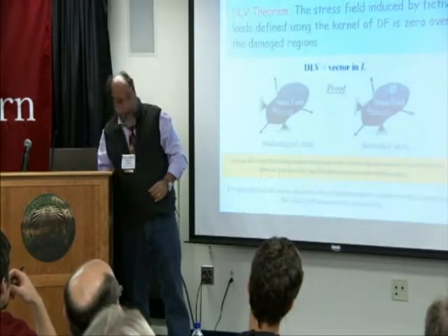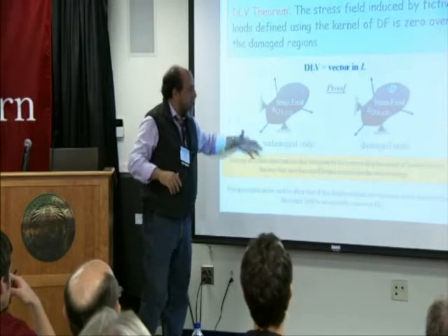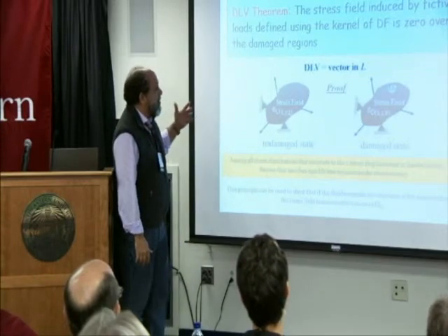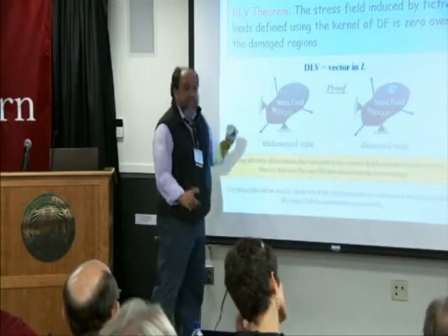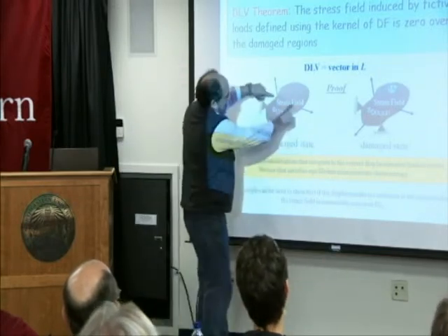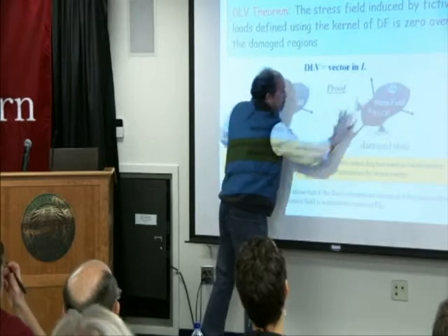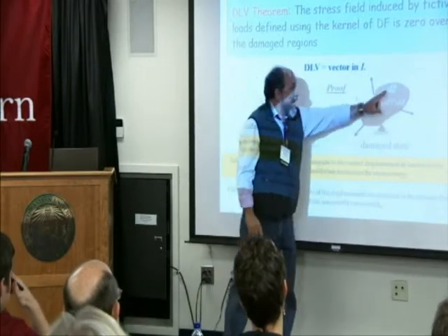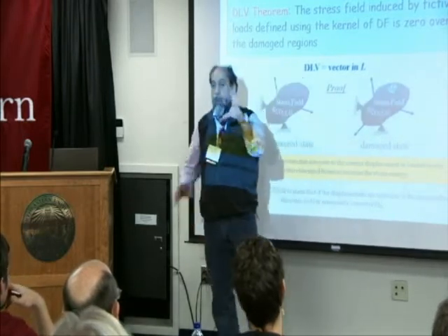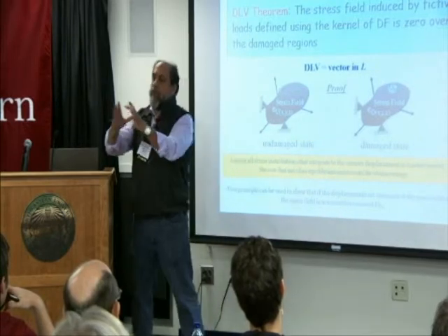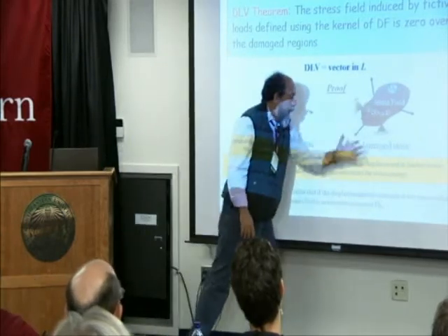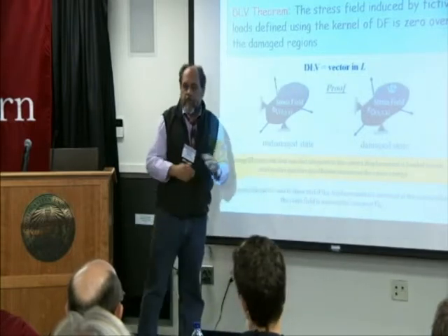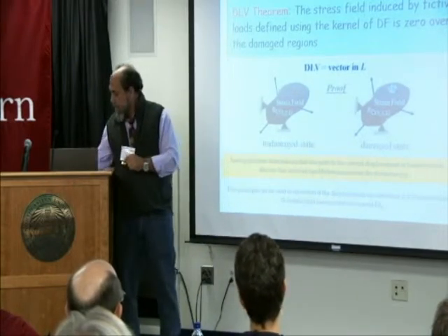There is then a theorem, which we prove being necessary and sufficient, but I will not go through the proof, but the point is this. If you found that vector, it can be proven that it will be exactly 0 stresses over the portion of the domain where there's been a change. It will be exactly 0 over here. Why? Because of minimum strain energy, because of this and that, but it's proof.